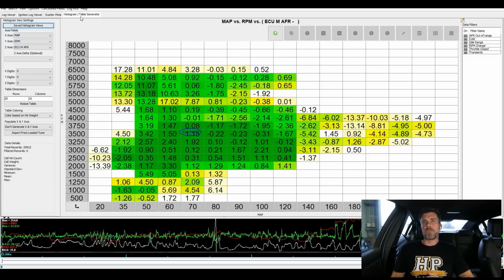And we can use our histograms for a wide range of different tasks as well. Here I am talking about fueling, and that is probably one of the key areas that I use histograms a lot in my own tuning, but it's definitely not limited just to that. We can use it for tuning our mass airflow sensor calibration, tuning our ignition timing if we're looking at knock events or knock retard, which we'll look at as we go through today's lesson. For the likes of HP Tuners and our GM tuning, I also use this for dialing in some of our idle control target tables, our base airflow running tables as well.